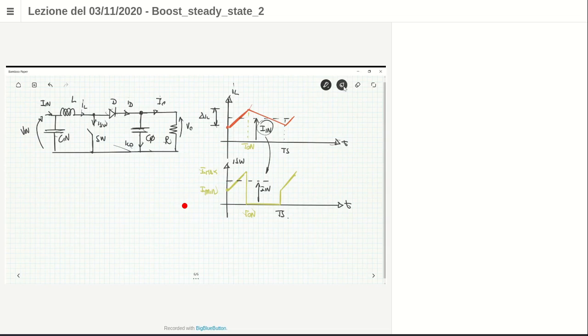These are the very important parameters for a switch. For a MOSFET, and this is a typical application for MOSFETs, the switch mode power supply, remember that the conduction losses, the power losses you have when the MOSFET is on, depend on its R-on resistance, the resistance due to the construction of the MOSFET that appears between its drain and source.